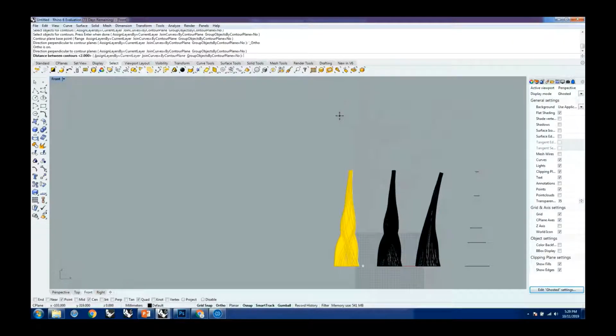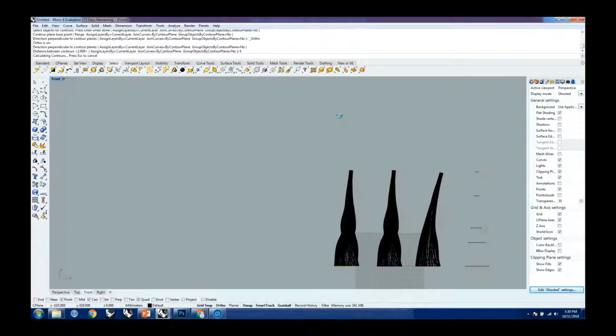So we're going to say, let's say, because we said that the total height was 200. So this is roughly 200 now because we bent it a little bit. So let's say it's 200, but we're going to cut it at 4. Okay, so 4 is what we say. Now you'll see that it is generating these curves. Basically, it's cutting the whole geometry and extracting only the end points of the curves. The extreme curves, I would say.